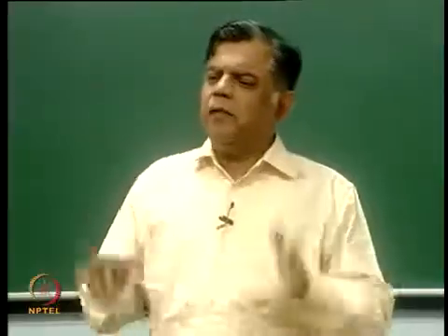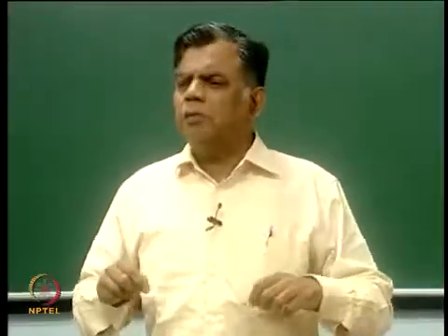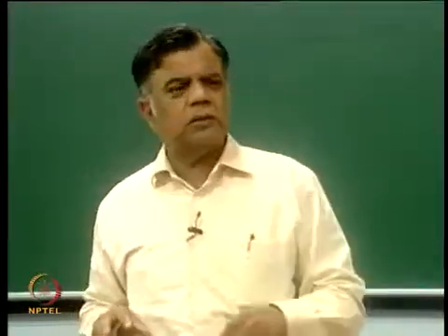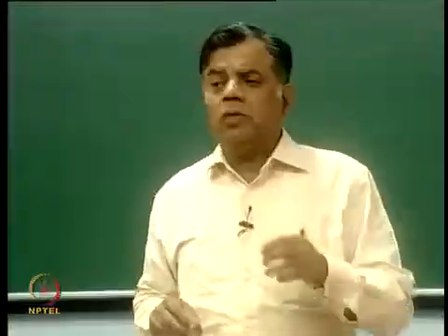You do not have to accept everything as it is said. You have to understand. Like convection is, in a way, not a fundamental mode of heat transfer. It is a modified form of conduction. It does not matter in your calculations, but you should understand as scientists, engineers. Similarly, Newton's law of cooling. So then, if it is not a law, what is it? It is simply a relationship. It is simply a definition of H now.